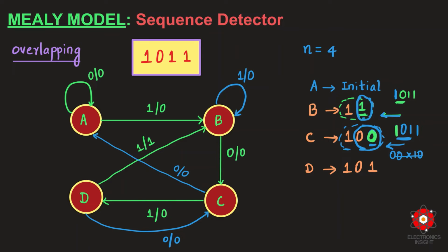So if you are going to get 0, 1010 is not a desired sequence. So if you get 1010, again start from the LSB. Start reading all the 4 bits. 4 bits it's not matching. So therefore I reduce the number of bits. I read 3 bits. 010 is not same as 101. It is not same. Therefore again I will reduce. When I reduce, it is 10. 10 is same as my first 2 bits in the desired sequence.